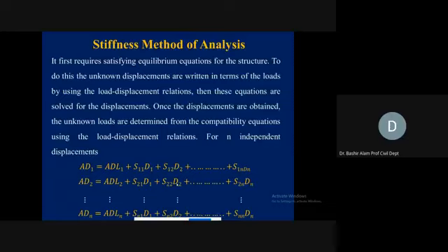Moment will generate there. So it means the equilibrium equation is not satisfied as in the original structure. Because of putting this constraint, we are having a moment which is a violation of the equilibrium condition.